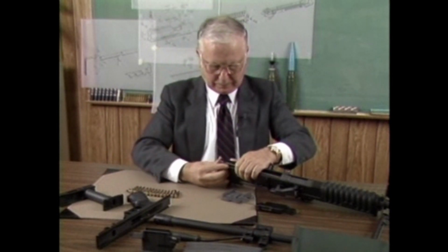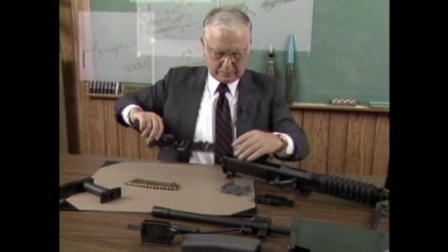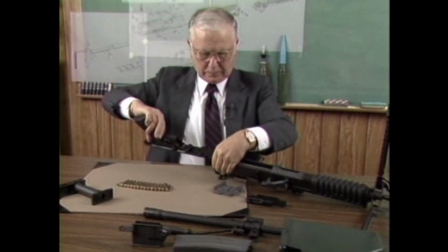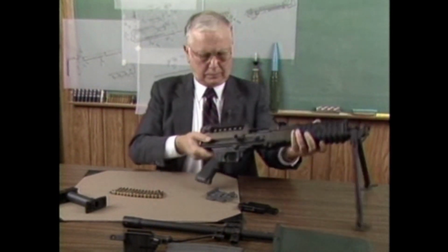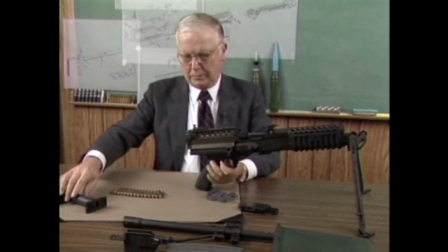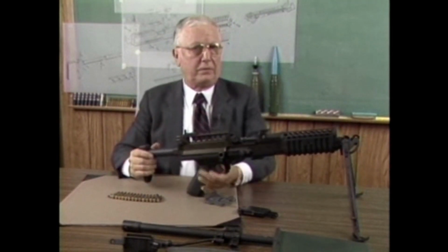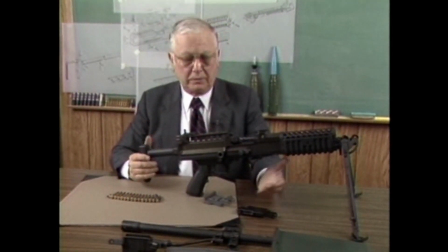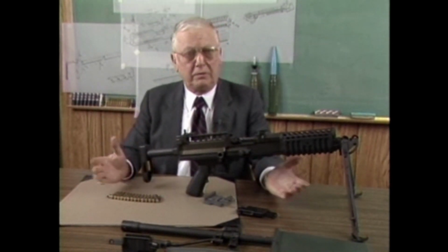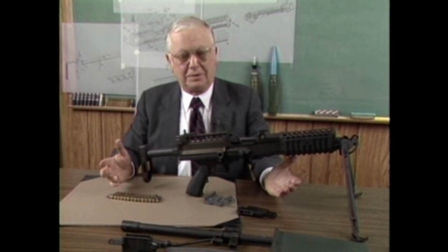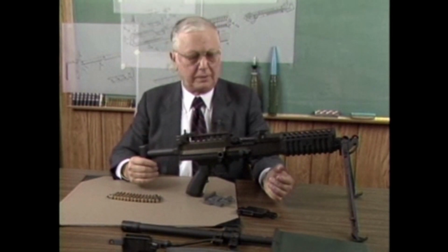In terms of development time, what do you say when you can take a part from an existing weapon, like that drive spring, and not have to do all the analysis and everything, but just adapt it to a new design? Well, it depends on the circumstance, but it could save an awful lot of testing. You already know that if this spring was picked because the cyclic rate was almost identical and the forces you need were identical, it could save you a lot of time and money in the development cycle by doing that.